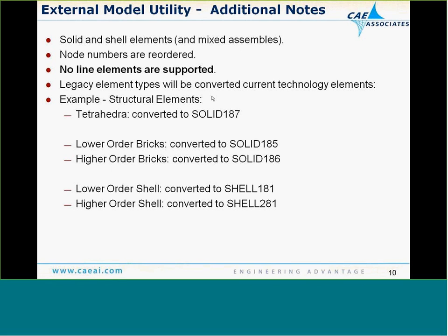And you'll find that any legacy element types that you're using, things like SOLID42s or SOLID95s, SOLID45s, they're going to be converted to current technology elements when they are read into the Workbench environment. So your tetrahedra will be converted to 187s, your bricks will be 185s and 186s, and your shells will be 181 and 281 elements.